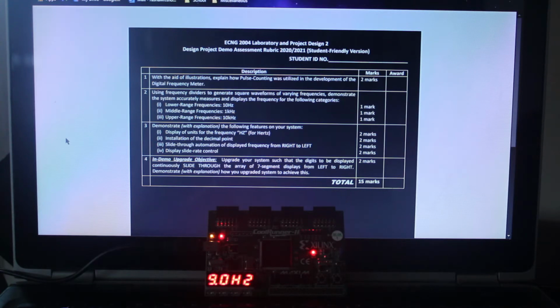That output of the AND gate went into the modular counter, and on each rising edge of that signal, the counter would increment. So that's how we got the frequency. It would be the number of pulses for 1 second, which is equal to the frequency.